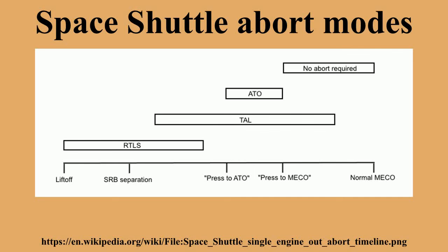Should the second SSME have failed at any point during PPA, the shuttle would not have been able to make it back to the runway at KSC, but the crew would be able to bail out. A failure of a third engine during the PPA maneuver would have led to loss of control and subsequent loss of crew and vehicle. Failure of all 3 engines as horizontal velocity approached zero just before external tank jettison would have also resulted in LOCV.